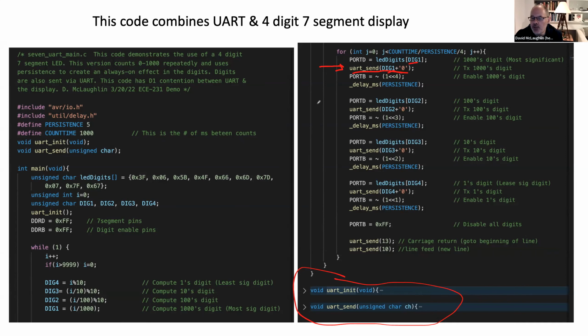So taking, for example, this pin here, it can serve as GPIO pin C5. That's port C, pin 5. It also functions as ADC 5. That's analog to digital converter 5. It can take an analog signal in. It's also the serial clock line for something called the I2C interface, right? And it also serves as interrupt 13 for port C. So each of these pins is capable of doing many things.